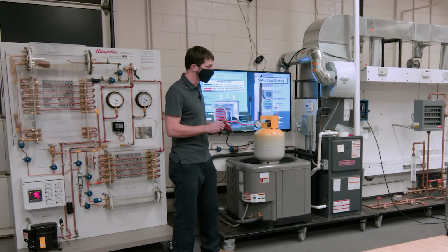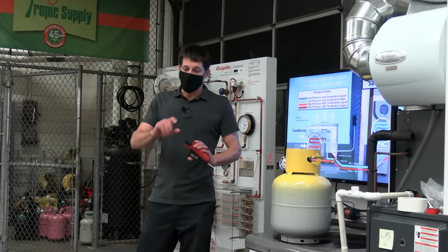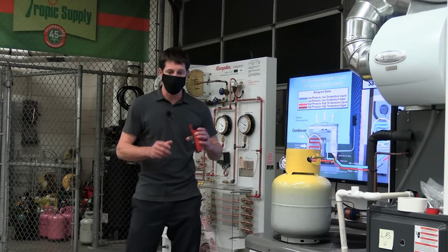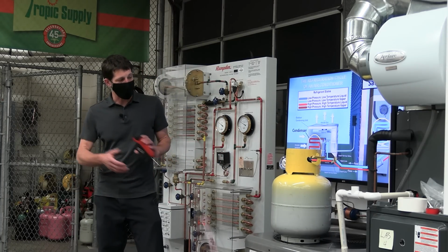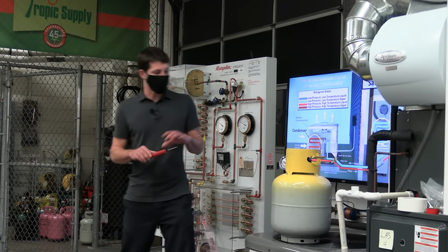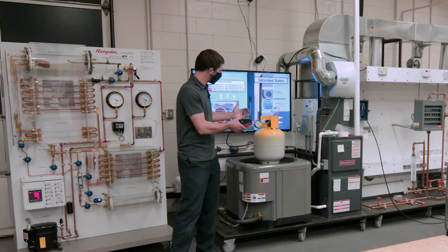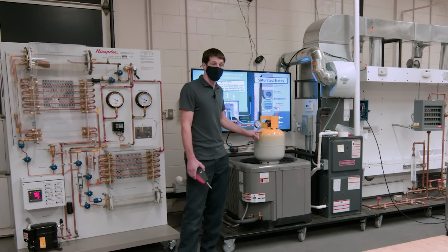And that happens from a loose hose connection when you're recovering the refrigerant out of the system. That's usually what happens, even if you tighten them and maybe the vibration of the recovery machine or something like that gets it loose. Or maybe you just want to check all that, and you want to purge the air out of the recovery machine. And some people vacuum the lines there. But basically, you got to get all the air out of the system before you recover the refrigerant into a recovery bottle.